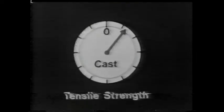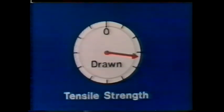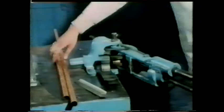It's much weaker than the drawn tube. Only 6 kilonewtons this time. Since the tubes were the same size, this means that the tensile strength has increased. So cold working has not only increased the hardness, it's also increased the tensile strength of the copper. It's brought about two useful changes in its mechanical properties. But what if we try bending a piece of cold work tube? Not all its properties are useful ones. Can you think what could be done to the copper to prevent this from happening?